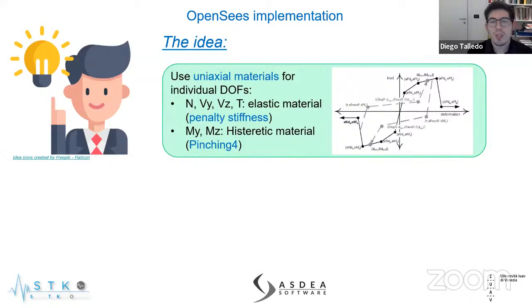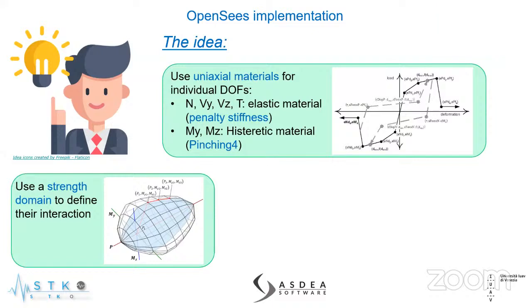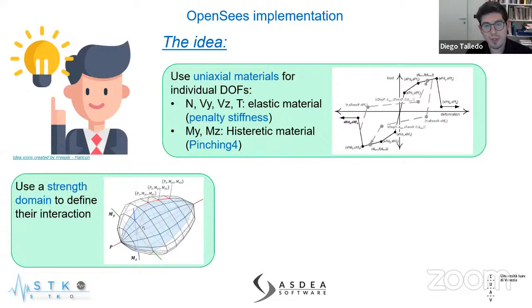For what concerns the two bending degrees of freedom, we are using a hysteretic material that is the pinching material that you can see in this picture on the right. Then we use a strength domain to define the interaction between these forces.